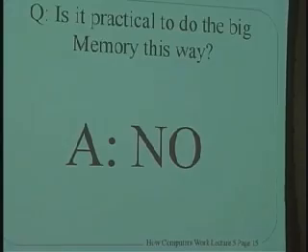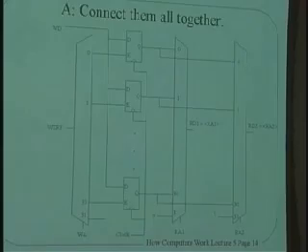How big can that register file get? That's a great question. I would say probably going beyond 1,000 registers is starting to push it. Okay? So on the order of 1,000. 1 million is way too high. Okay? 1 billion, which is what we're getting close to now in terms of RAM these days, much, much too high. Each register is 4 bytes. Where each one of these registers is 32 bits, yeah.